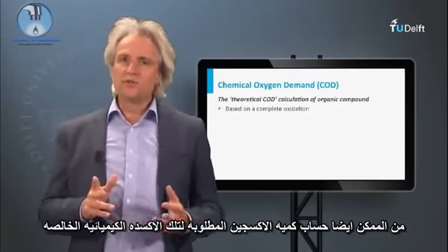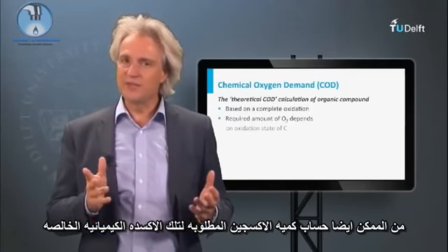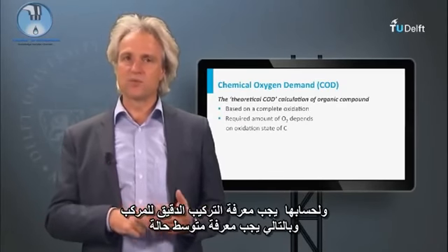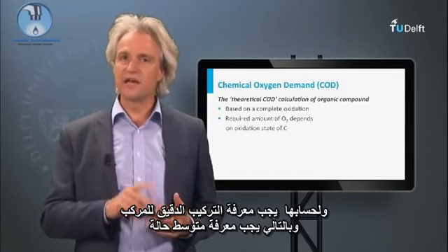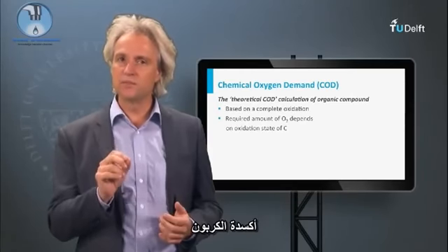The oxygen requirement for this pure chemical oxidation can also be calculated. For this, the exact composition of the compound and thus the average carbon oxidation state must be known.